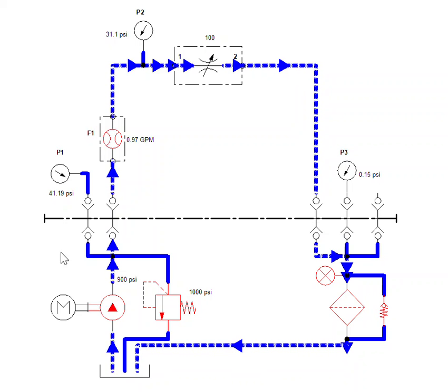And you can see pressure P1 near the pump inlet is not very high. Downstream at P2 a little bit lower, because there's some resistance to flow from here to here, not much, but a little bit, so this pressure is lower. And near the end, pretty close to the tank, P3 is very close to zero, when the flow just goes through the filter and back to tank.